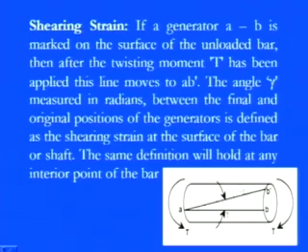Whenever a shaft or a bar is under the application of a twisting moment or torque, we have a state of pure shear stress acting on these bars, and due to that we have a distortion which can be easily computed in the form of strain. These strains are known as the shearing strains, and they always act along the plane, or we can say along the circumferential part, which can be easily computed as shown in this particular figure.